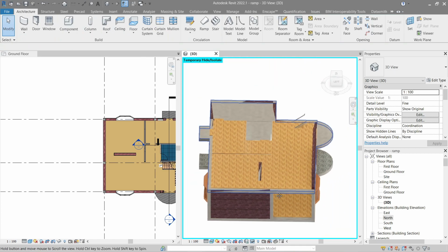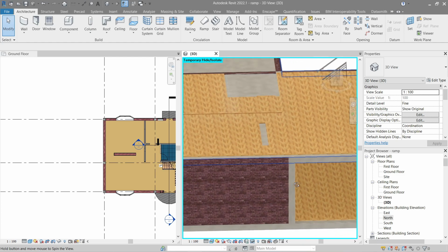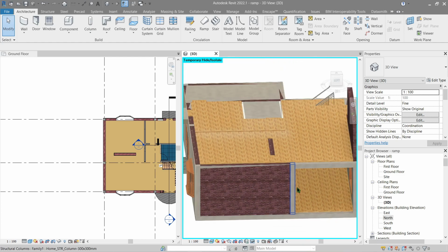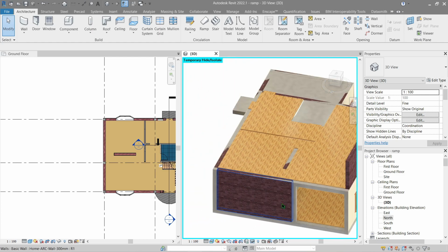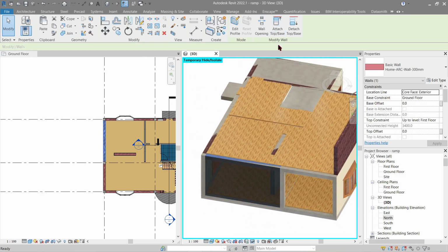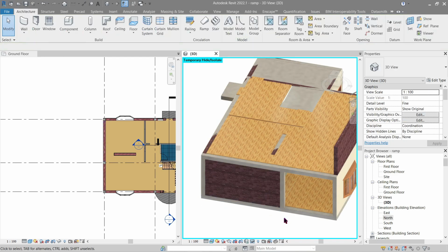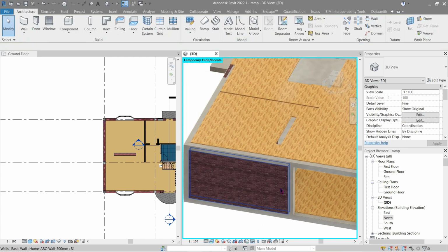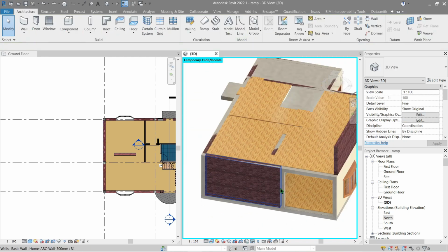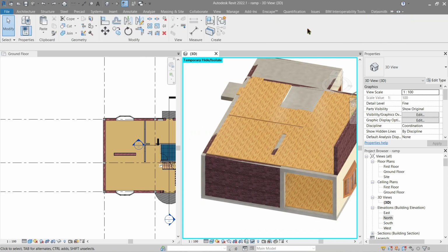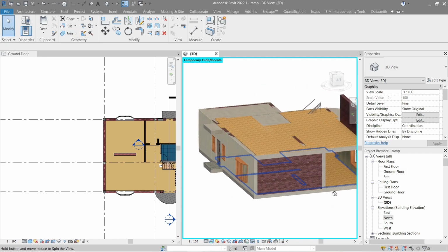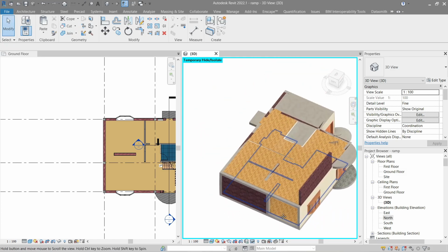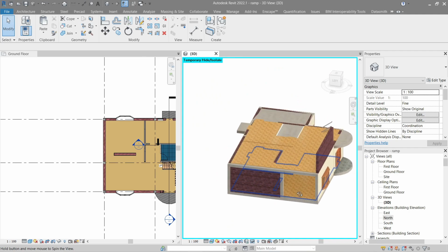You see some clashes happening. The reason why is because the walls are clashing with the slab that we just copy pasted into. Now, your choice will be either to click this, go to top base, and click the bottom here. As you see, everything's gone. Or undo, go back to modify, and join that. There. So do the same for everything, and let's see what happens from there.